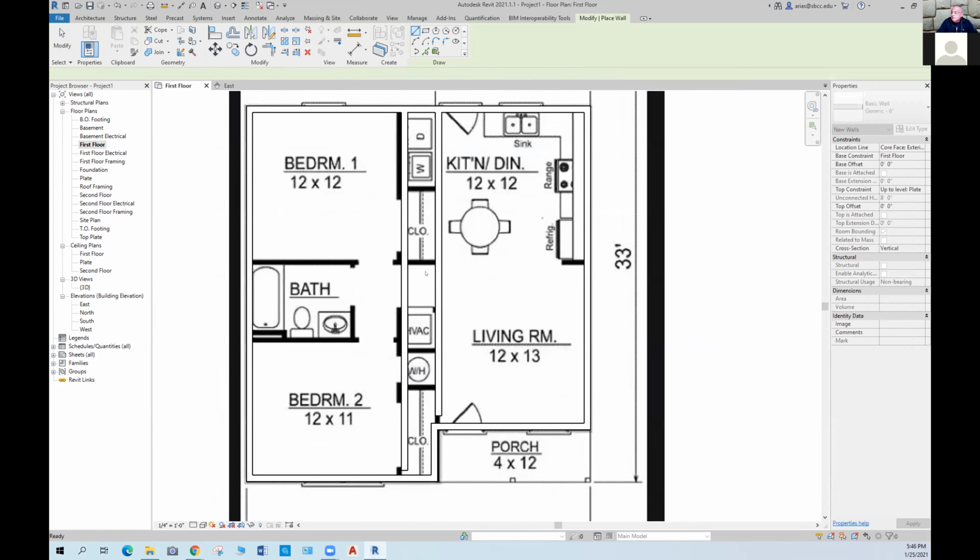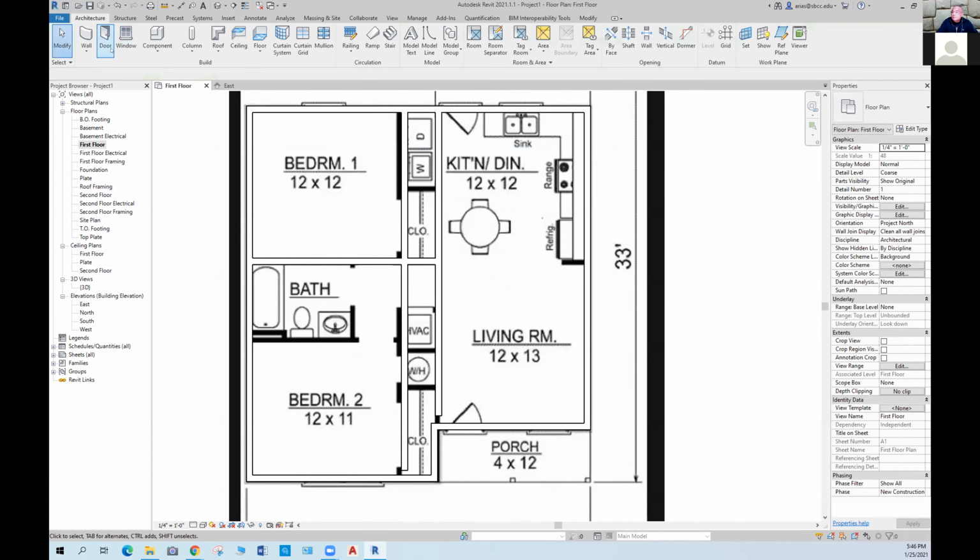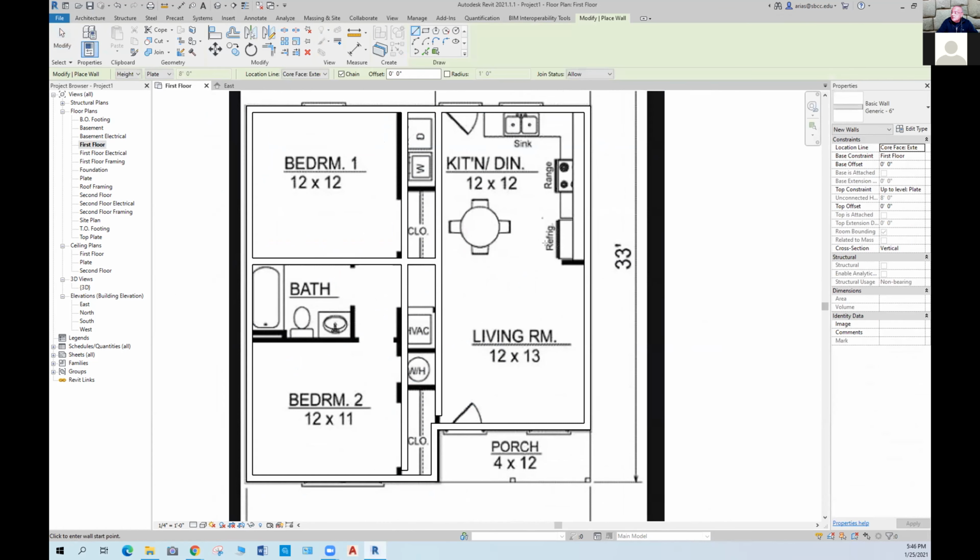And it doesn't need to be precise yet because we will make sure that the dimensions are precise in the next step. Architecture. So walls everywhere they go. Not worry about the heights because I already specified the heights.